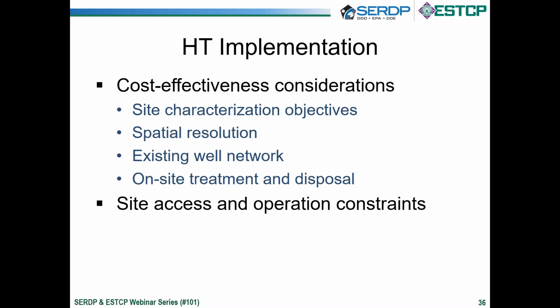For example, if you are doing it for source zone delineation or source zone remediation, you might have a need for a higher resolution information. Or if you are doing pump and treat system, you might be able to live with a larger scale characterization. And also, it's very important whether you have existing wells available for the hydraulic information collection.